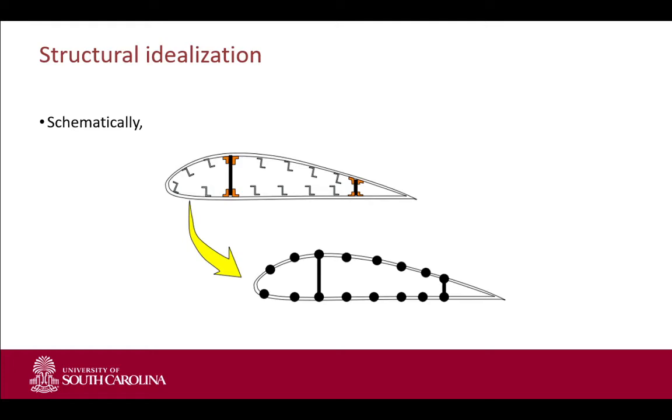So basically what we did, if we summarize everything in a figure, we went from the top figure to the bottom figure, where the stiffeners and the equivalent masses of the skins are lumped into one area that we call a boom. And we can calculate those boom areas by looking at the stress distribution in the real structure and an idealized section, and then these two must be equal to each other, so therefore we can isolate the boom areas.